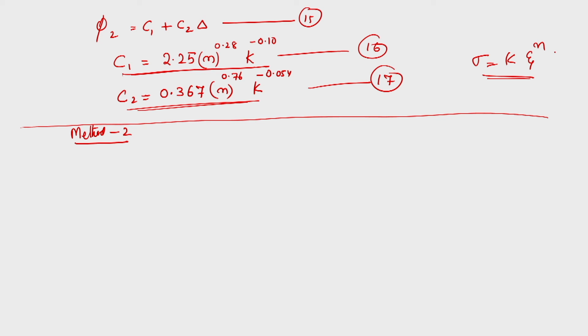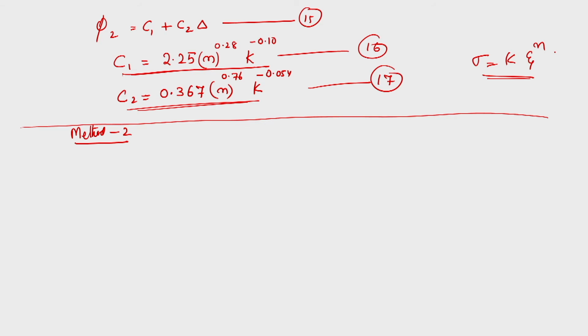In this, the stress strain curves are drawn at different conditions. You are obtaining the stress strain curve for drawn wire, maybe drawn for different reductions, and then they are compared with the stress strain curve of a fully annealed steel. Then the initial flow stress following any given strain in wire drawing is greater than the flow stress produced by straining homogeneously to the same strain in simple tension. So, that is what you will find out, and this difference is due to the redundant deformation.